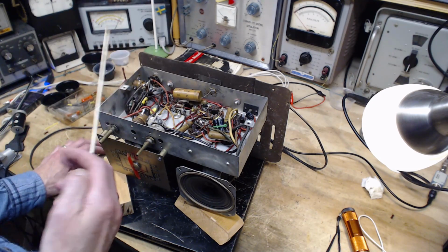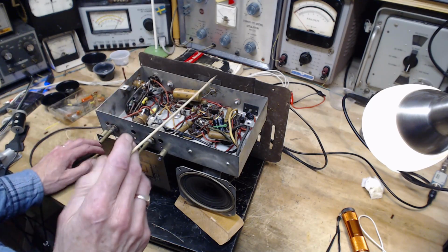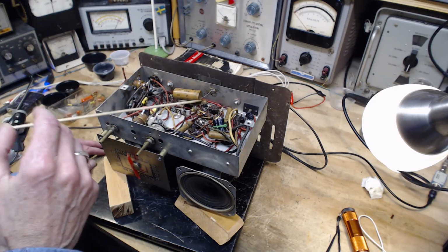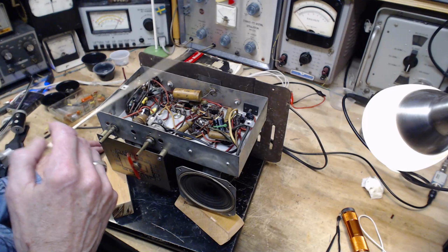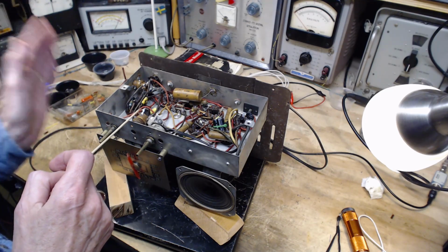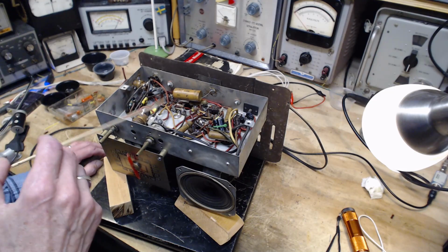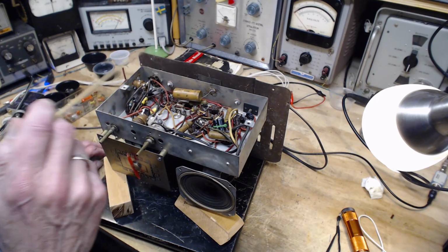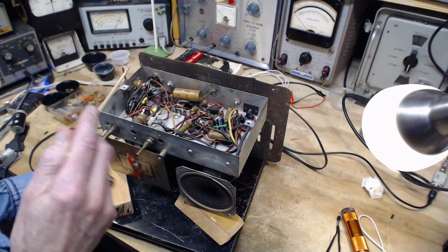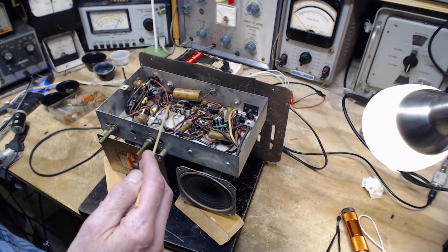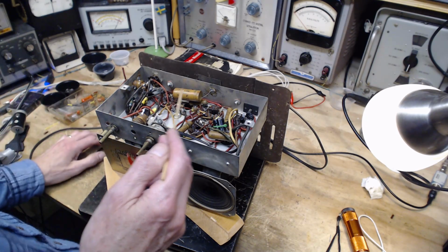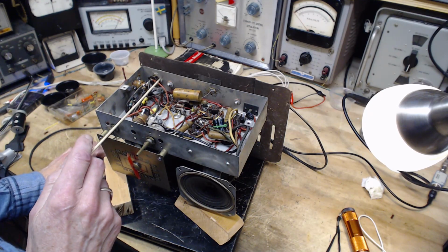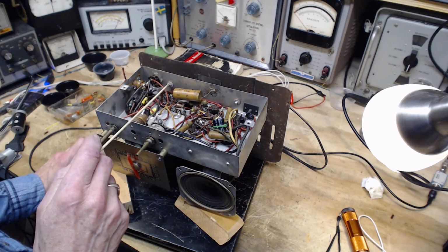So what happens if that AVC capacitor is a little bit leaky? Well, it's hooked up between the AVC line, I'm pointing at nothing here, by the way, with this stick, it's hooked up between the AVC line at the grids of the tubes, or near the grids of the tubes that are going to be affected by the AVC, and the other side is hooked up to B minus. If that capacitor is a little bit leaky, it can bleed down the charge fairly easily in this circuit, and the result is your bias voltage will not be where it should be. It's going to be less than what it should be.